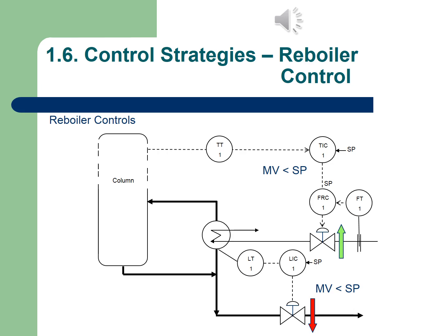So this is not a cooling heat exchanger, it's a heating medium exchanger. So adding more of this heating medium through it means that the bottom product that is in actual fact in contact with this heat exchanger, the temperature will increase in that. Okay. And then as the process continues, there's also feed that goes into the column, so the level of the bottom product will increase. Sometimes if the level increases too high, we need to feed off some of this as the final bottom product.